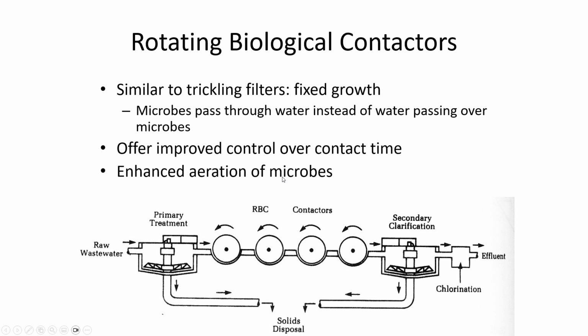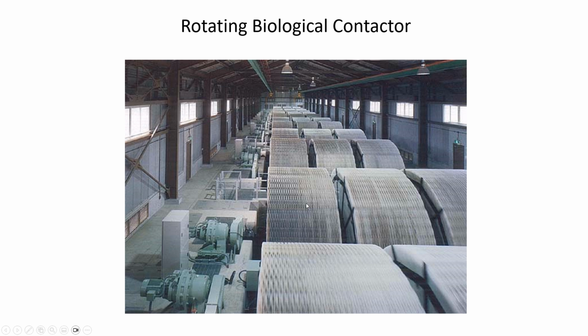in a secondary clarifier. So just to give you a schematic view of what's happening, the water that comes off of the top of a primary clarifier goes into this series of pools where the RBCs are exposed to the water, they're consuming the BOD, they're exposed to oxygen, and there's very little electricity requirement. It doesn't use much electricity to rotate these.